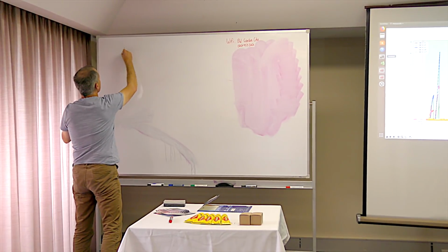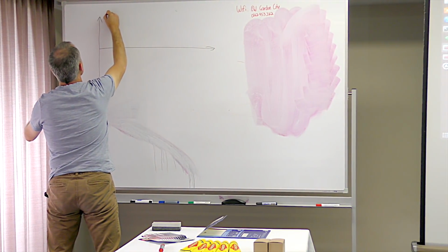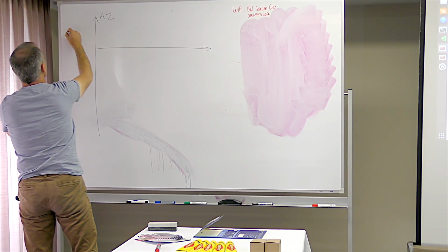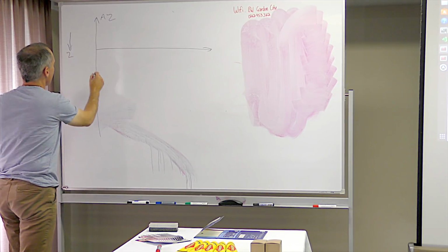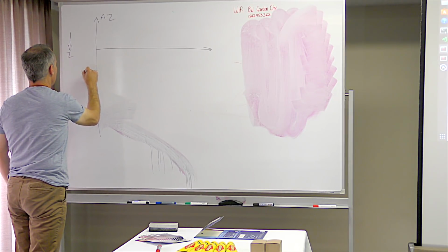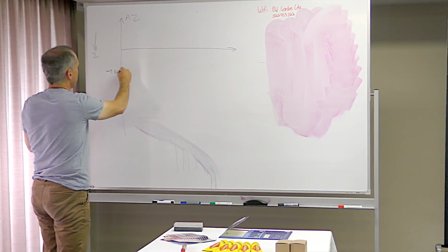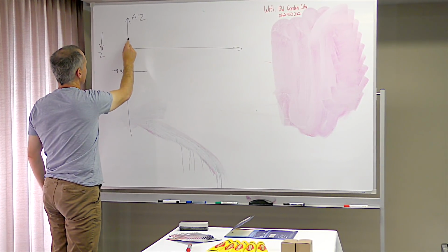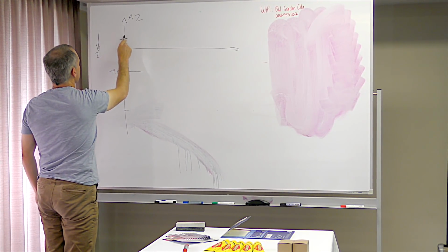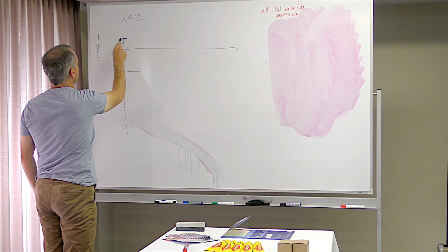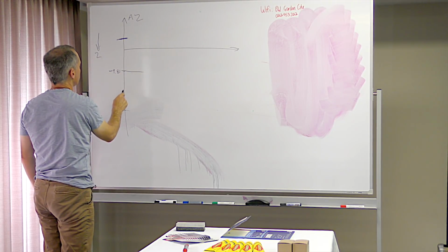Okay, so we have acceleration in the Z direction, and remember that Z is down. So it's measuring minus 9.8, there and thereabouts, plus a bit of movement of the copter. Now I'm going to pretend I've got a sensor that can only measure between -2 and +2.